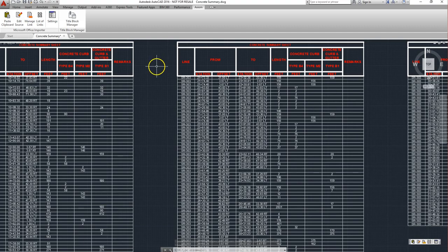Now this information is automatically linked back to the spreadsheet it came from, and what that means is whenever you open this drawing in the future, or someone else with the software installed opens it, the software will immediately check to see if the spreadsheet has changed, and if it has, it'll update the data in the DWG. The idea is for you to become used to it naturally staying up to date, so that it's not something you have to monitor, one more thing for you to worry about. It's just something reliable. Now you can update them at will whenever you want as well.